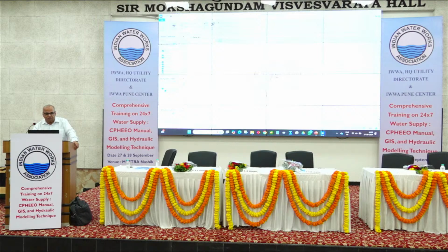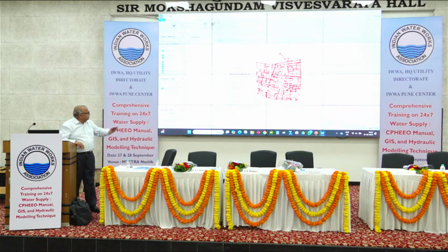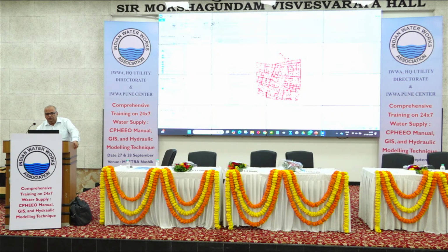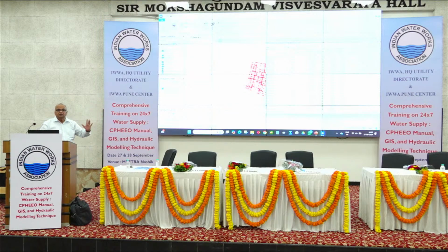So now that's what I was telling you. If you right click, now here is one facility. You have to select right click and say edit data and edit junction. Means all the junctions will be selected and their attributes will be shown. Edit group, I am saying junction table. Madam has told you about FlexTable. So these elevations you will see. Elevations from the contours are assigned to each and every node.